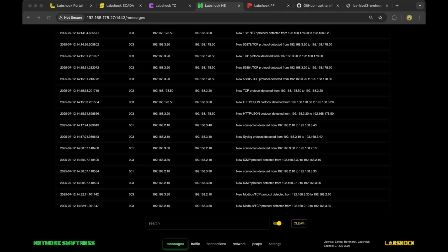If we have a firewall between level 3 and level 2 with good rules, I believe this will not receive commands from the new IP. If you have firewalls, the question is, are your firewalls working as expected and you don't have any misconfigured rules? Because it's very hard to maintain and handle firewalls in critical areas. Misconfiguration on the firewalls is one big question.